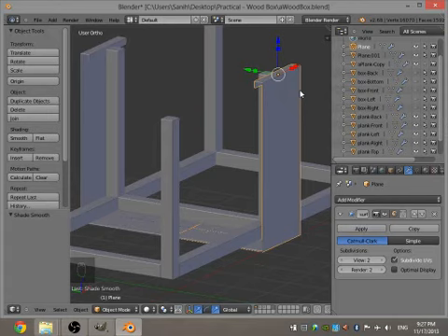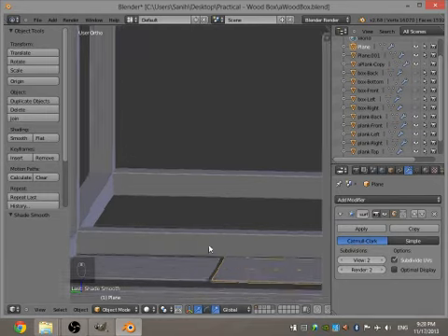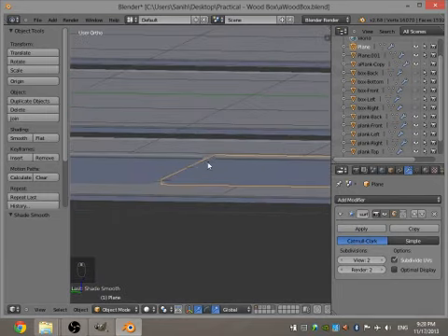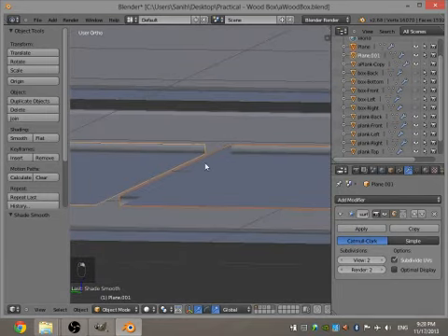It's just something that you do by mistake, when planes overlap, plus and minus flip. When flipped to a negative, it should be on the other side, it should be a dark shade. So that's an error. So sometimes you get this error when you're connecting two pieces.